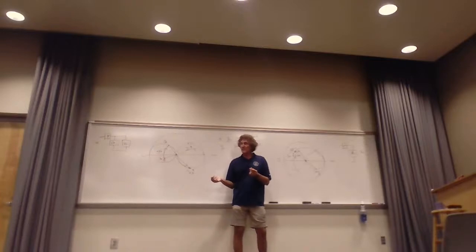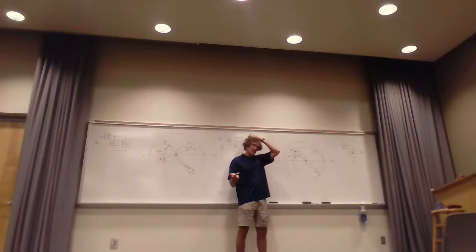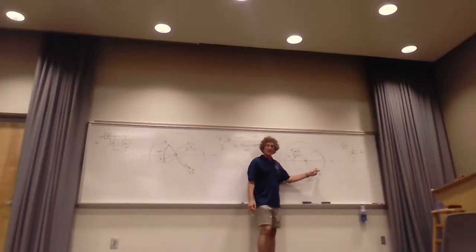And if it's an admittance, this is something to keep in mind, I've got a negative j something here, and I want to get to this point, so I'm adding a positive j something, and that would be a capacitor. An admittance, positive j, correct?